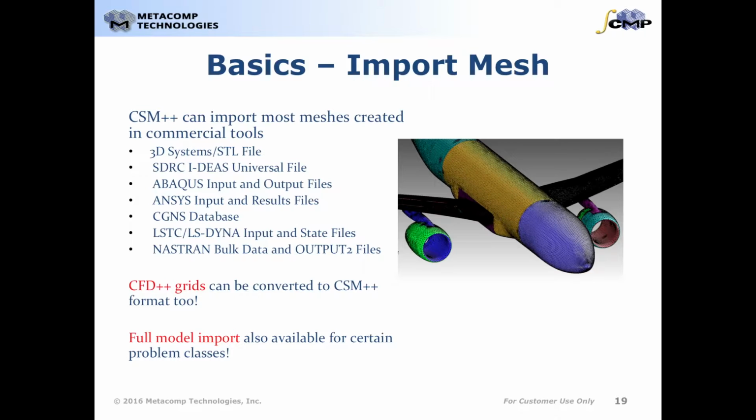CSM++ can also import most meshes created in other commercial tools such as Abaqus, ANSYS, Nastran, and others. Additionally, CFD++ grids can be converted to CSM++ format. In addition to just importing meshes, CSM++ can do a full model import for certain problem classes such as Nastran input files.